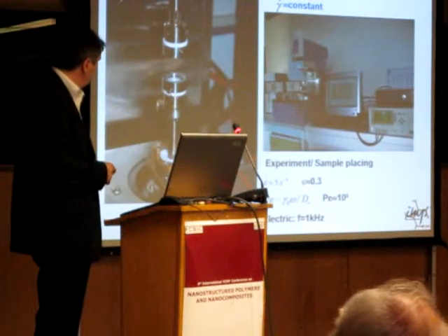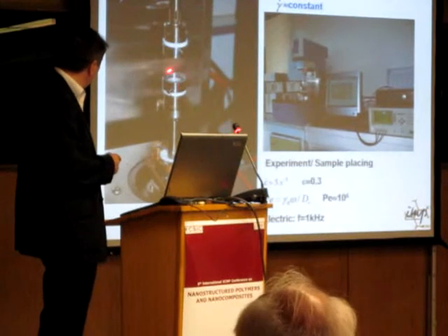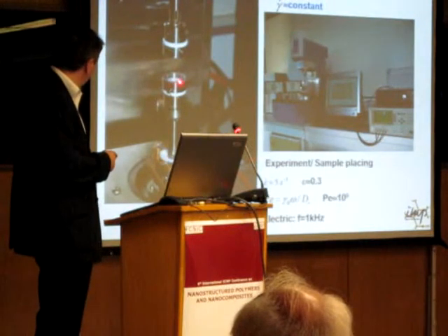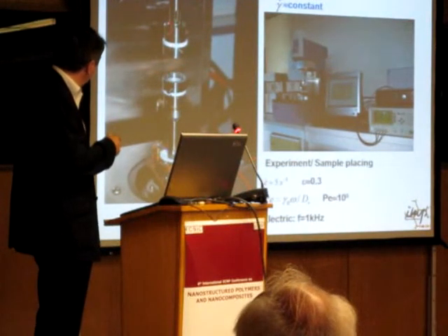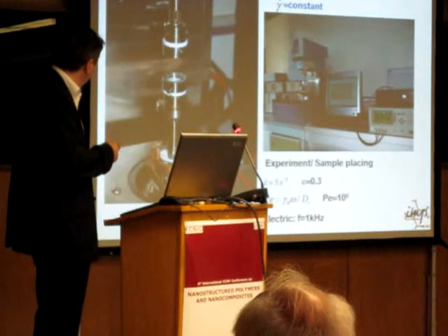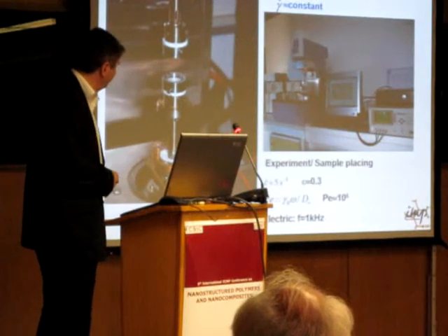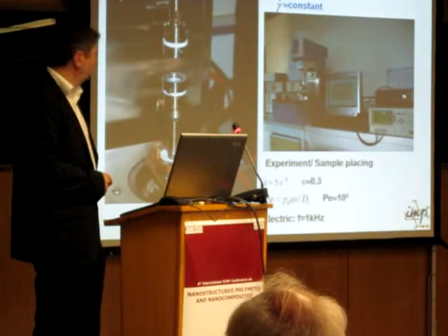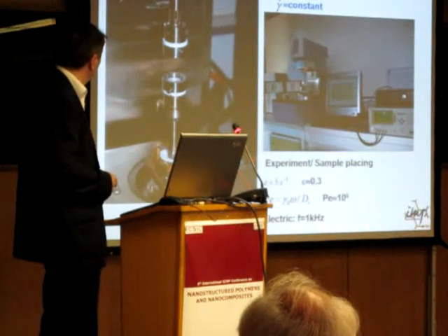Here, rather than studying the influence of pressure, we have used an elongation deformation in the first part of the experiment. We put the film, a sample of about 1 millimeter, and by displacement of the upper cell here, we applied an elongation deformation of about 5 reciprocal seconds. So the total deformation undergone by the sample is 0.3, so we can calculate the different Weissenberg numbers, for example.